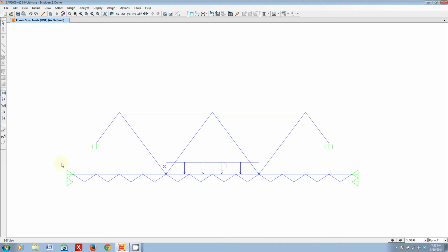Is it going to go to these supports at the girders, or is it going to go up through our tendons into our overtruss and go to these supports? And my prediction is it's going to go through the overtruss, because remember, the rods are stiffer, and that means they'll attract more of the load. The girders are just going to flop around and not really do a whole lot, but you need the girders, because you got to distribute those loads up into your overtruss somehow. Somebody's got to do it. It's a dirty job, but let's double check that.